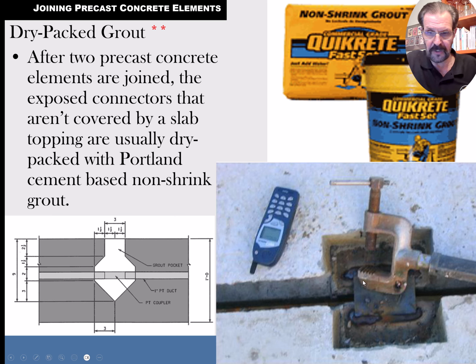And you can see they got a chunk of metal plate. Often they show up at the job site with a whole bunch of chunks of metal plate to help bridge the gap, because you've got to get an electrical connection across here to weld it, and that's generally done with a big chunk of plate that might be 1/4-inch, 1/2-inch metal plate that they would weld across from one to the other.